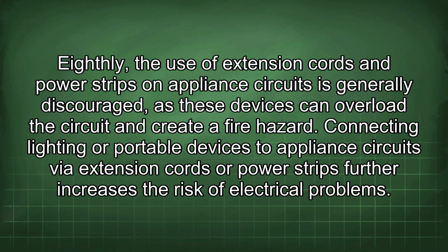Eighthly, the use of extension cords and power strips on appliance circuits is generally discouraged, as these devices can overload the circuit and create a fire hazard. Connecting lighting or portable devices to appliance circuits via extension cords or power strips further increases the risk of electrical problems.